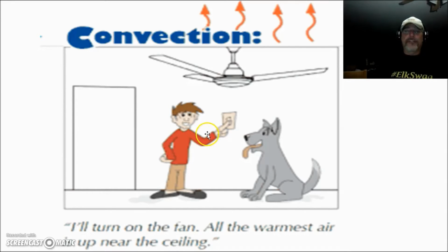Yes, convection. So the warm air is going to move up to the ceiling. As you know, hot air is going to float, or hot air is going to rise. So what some people will do is they'll turn a ceiling fan on, even in the winter. I actually do this. I have ceiling fans in my home. So in the winter, what I do is we'll turn the ceiling fans on, and we'll have the air blow this direction, and it will take the warm air that's up on top of the ceiling and move it to the sides of the room, so to get it to circulate around and to move the hot air better throughout